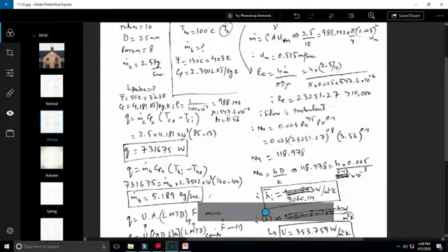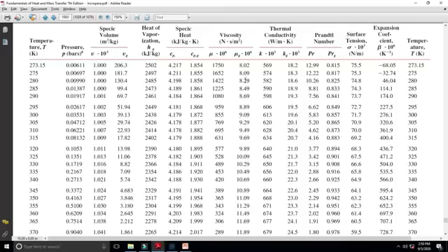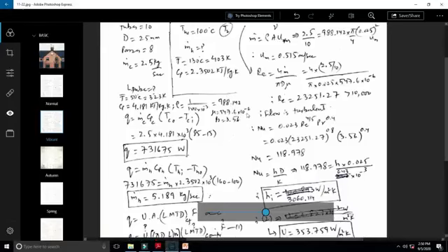Upon interpolation we get a value of 547.6, and if you note, those values have been provided by multiplying with a million. So the actual value would be obtained if we divide it by a million. Therefore you will see over here that it has been divided by a million, meaning 10 to the power minus 6. So that value of viscosity will be put over here, 547.6 exponent minus 6, and we get the Reynolds number as 23,251.